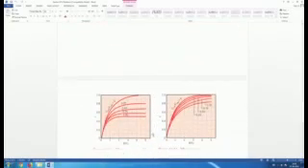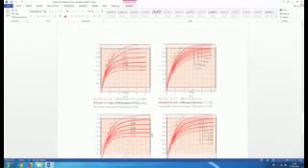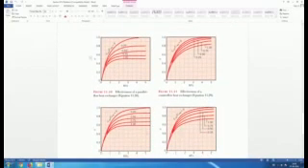And the figures that I was talking about are also from your text. Here you see the effectiveness epsilon of a parallel flow heat exchanger, which is equation 11.28 on the previous page. If you know the value of NTU, you find C minimum by C maximum, read that, go up to that point and find out the epsilon, or effectiveness, of the heat exchanger. Once we solve a problem in the next class, it would be even more clear to you.